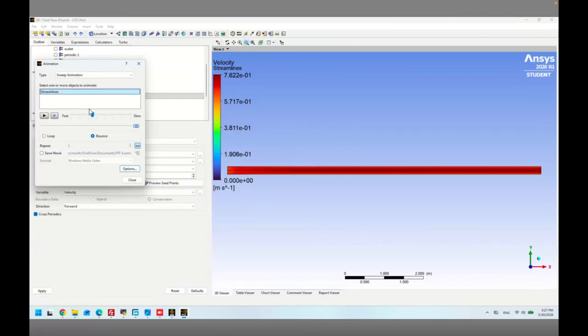For the animation, we click streamlines and then we'll make it slow. You have to disable the infinity option. If you make it infinity, you will crash. So let's run it for only one repetition. You see here, like we mentioned, we set it up with these spheres. We see that the ones closer to the boundary are very slow, but at the very center they are the same velocity and they all move together.